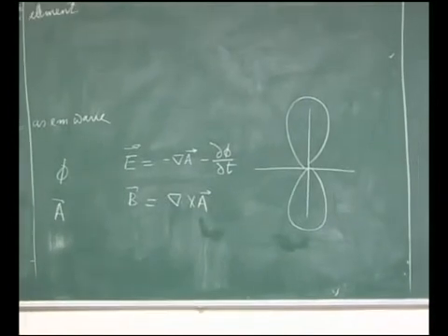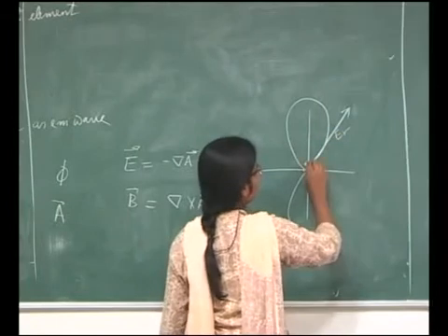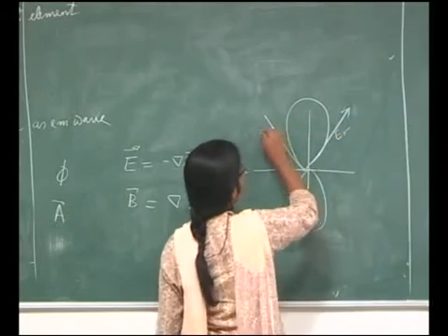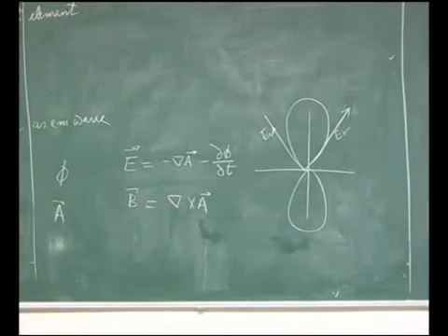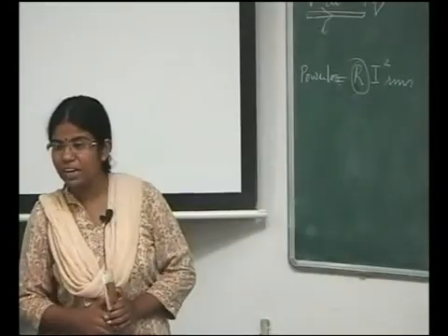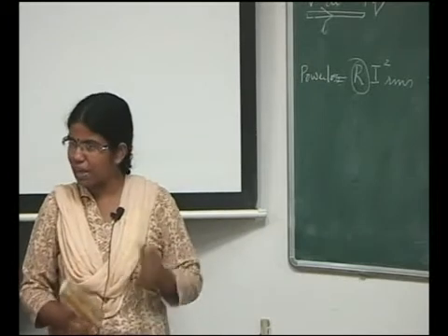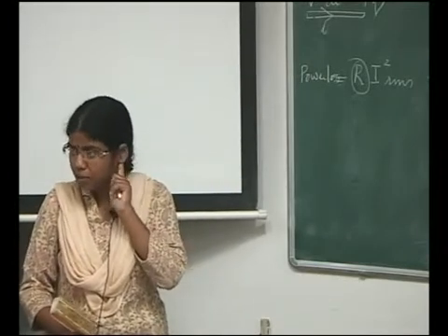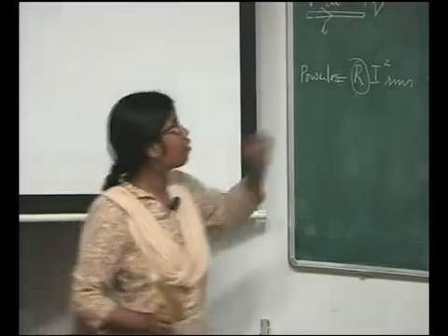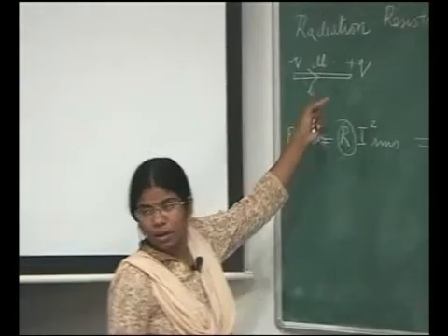So, now if I calculate the radial electric field intensity here, and if I can calculate the corresponding magnetic field, then I can calculate the total power that is being radiated from the Poynting vector. If I can calculate E and I can calculate B, then I can calculate the power that is being radiated from this antenna, from this current element due to a small current I.